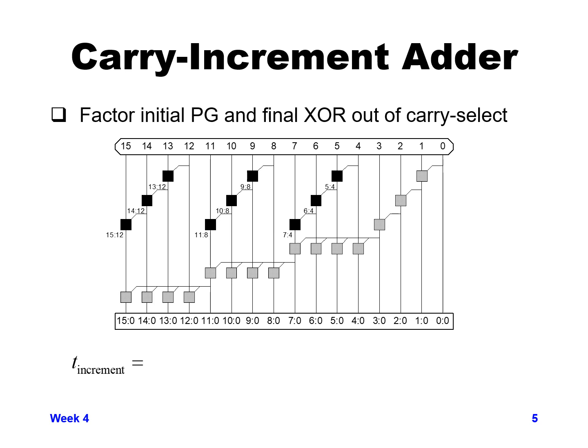So in effect, we now have 6 delay elements in this design, as opposed to, if you remember from previous designs, the best previous design we had was 7 delays. So this carry increment adder can now bring that down to even 6 for a 15-bit adder.